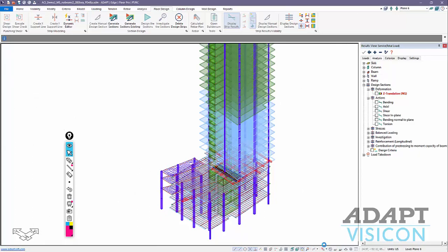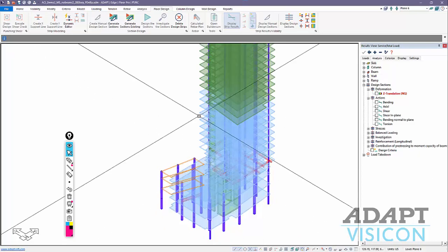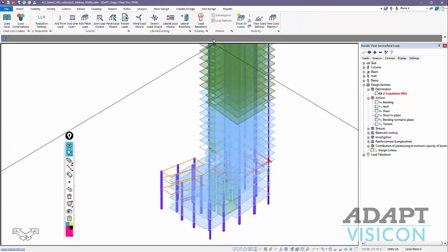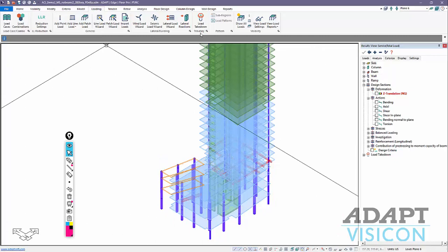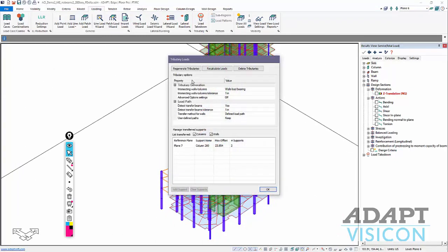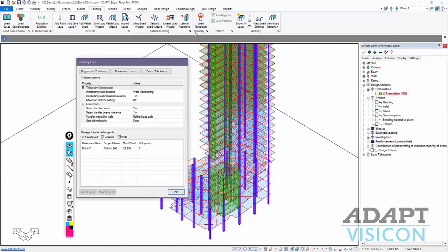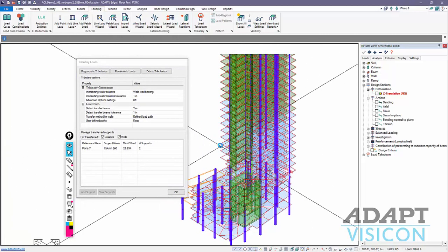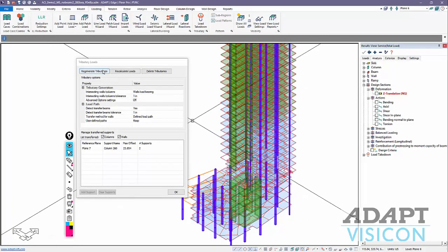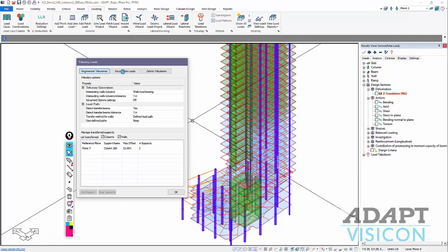So if I take this model now, which includes loads on all levels, and I use load takedown, I'm going to generate Voronoi-based tributaries for the structure. And so we'll regenerate and recalculate the tributary load takedown based on these tributary regions that the program has produced.